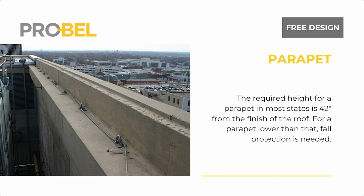Okay, so once you've reviewed all these factors, it's time to create a new design. You should separate all the roof plans into a new document to begin the design process. And if the different roof elevations aren't all on one document, you gotta merge them. Have any relevant documents such as roof details, elevations, landscaping if it's applicable to the roof, isometrics, overall building section, and any other plans that would impact the roof, make sure you got them all together in one.